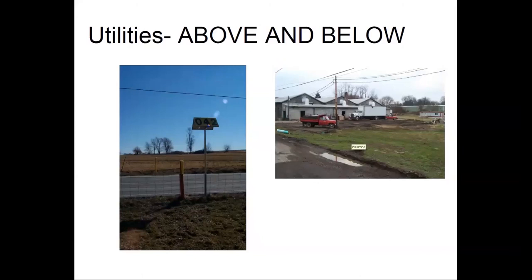You need to make sure you know where the utilities are. I have had the misfortune of talking with a farmer and saying, where are your utilities? And we went along with the spray paint and we painted where they said that they had buried the utilities. And we were very careful to design and plan around where these utilities were.